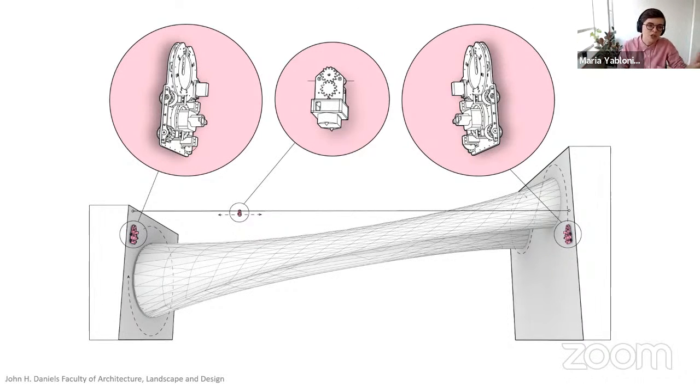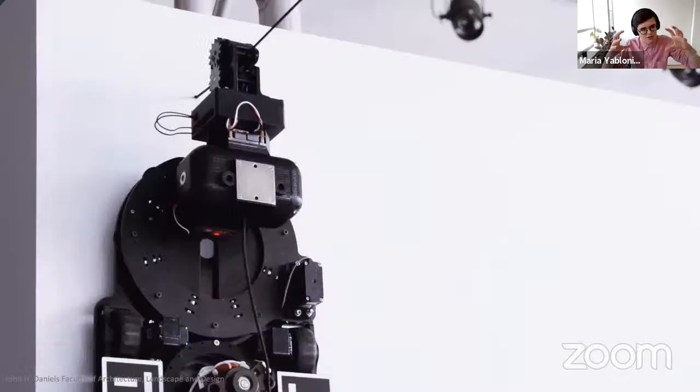The second type of machine here was this shuttle robot or thread walker. It has acquired multiple different names throughout its life. Basically, that robot only travels along a single thread of filament, and in this case, that was just cable. By traveling in between the 2 walls, it carries a bobbin of filament material. As you can see in this image, there's this tiny little box where the filament sits inside. By traveling between the two wall climbers, this thread walker passes the material from one side to another and allows the fabrication space to extend from these two flat surfaces into the whole volume between them. So these are some of the videos of the actual fabrication process.